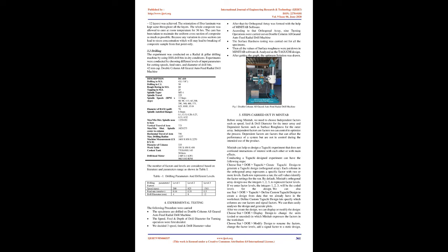3.1 Fabrication of GFRP composite. In this experiment, GFRP composites were fabricated by hand layup technique. For the fabrication of GFRP composite, epoxy polymer, Araldite LY556, and hardener, HY 951, were taken in the ratio of 10:1 by weight by using a micro-weighing balance.